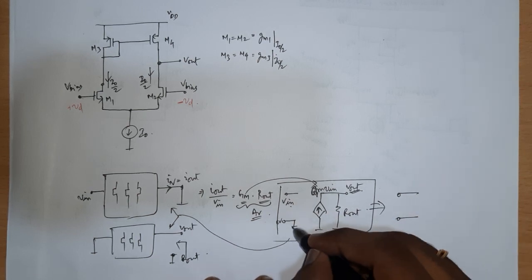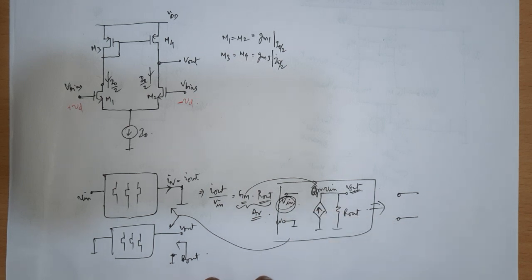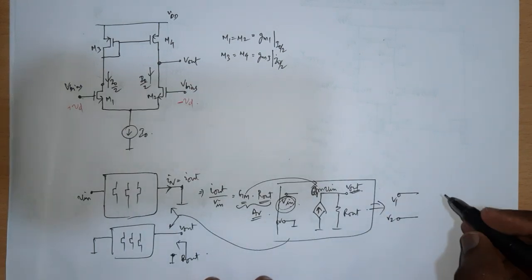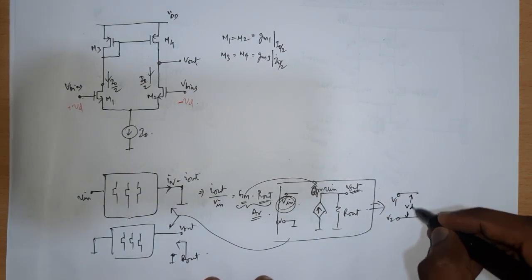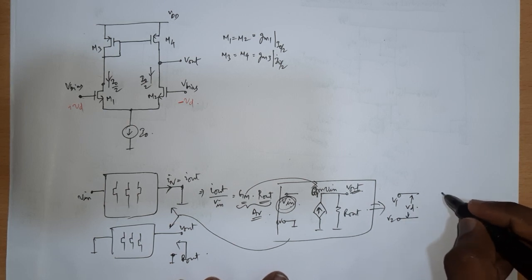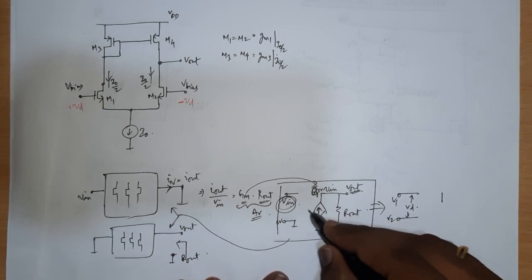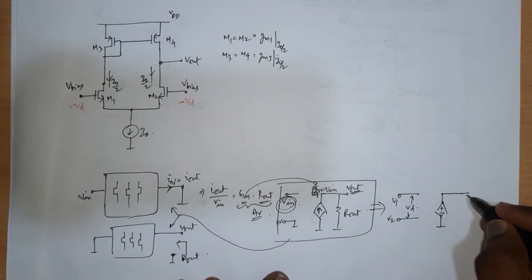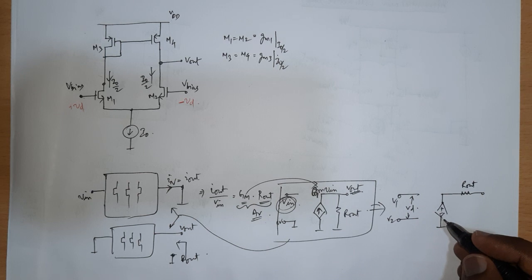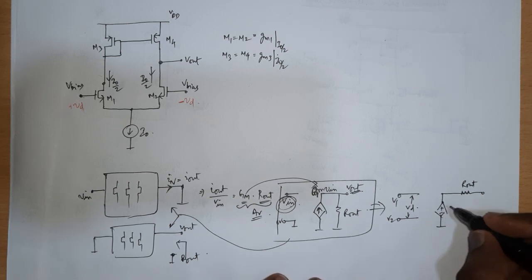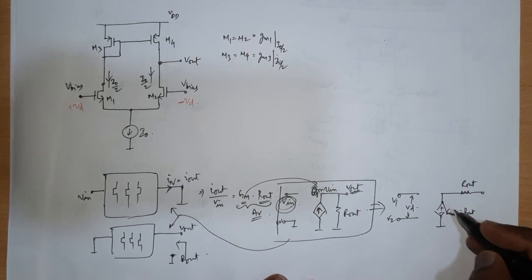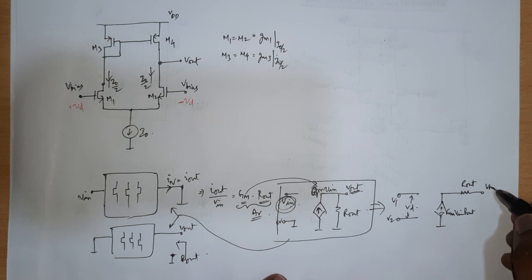two inputs, and I've denoted V in alone on one side, but it could always be V1 and V2, which is Vd and minus Vd. This difference is going to be Vd, V1 minus V2, and then you put a Norton equivalent, so put a Thevenin equivalent for this, in series with a resistor, and this is going to be R out, and this is appropriately Gm V in times R out, right? So Gm V in R out will be your Thevenin equivalent, and this will be your V out.